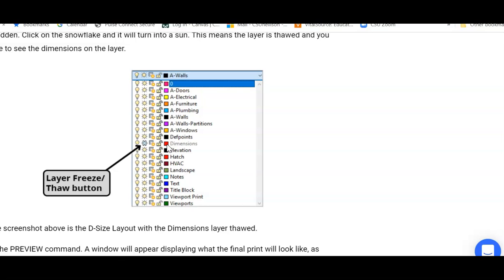And we also want to draw each of our elements on a different layer so that we can potentially isolate the layers and turn things on and off. As drawings have more and more information on them, we could say, okay, I'm going to freeze all the text or all the dimensions, and I just want to see the columns and the footings.